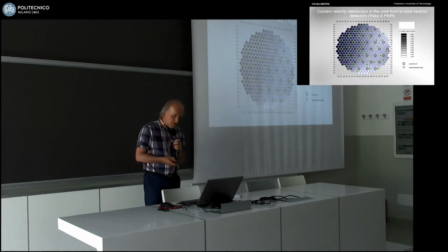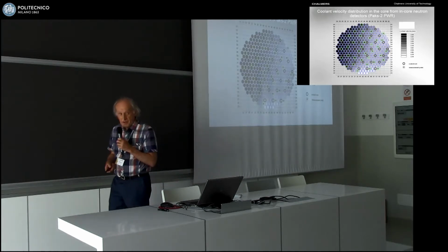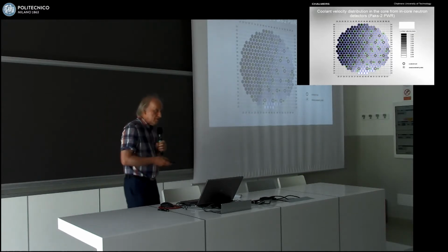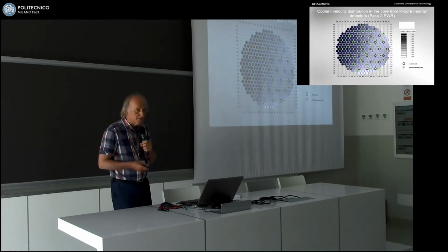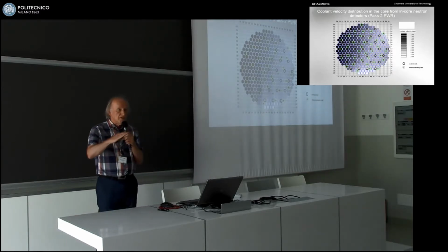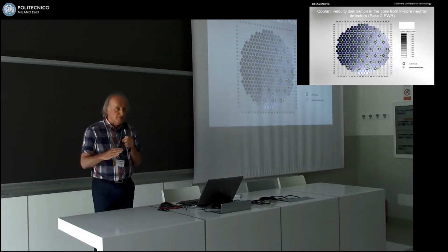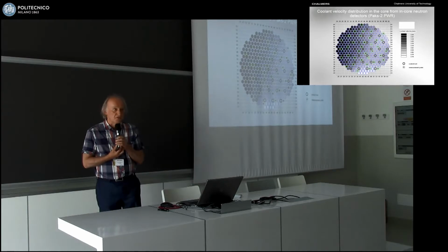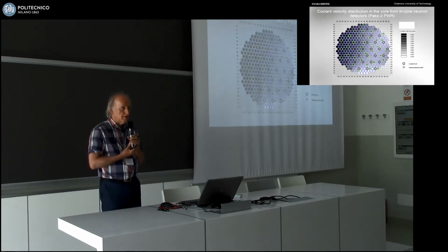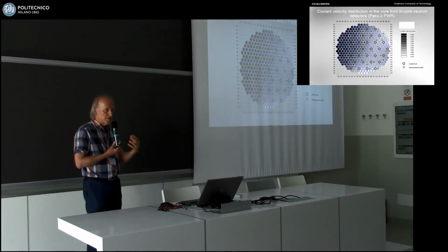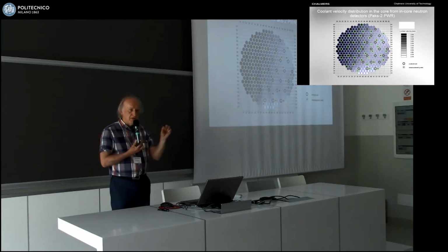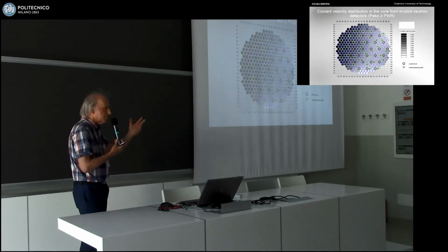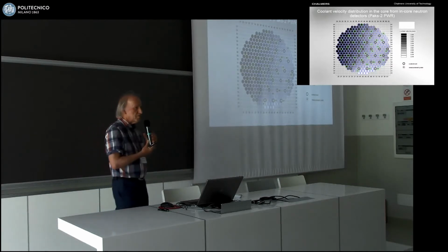I'm very proud of it because that's my Hungarian colleagues who did it in the PAKS reactor, in which there are in-core detectors. And from the signals of these in-core detectors, they found out that there is a non-symmetric distribution of the flow velocity. And why I think that this is a feat is that in a boiling water reactor, to measure the velocity is not complicated, because the perturbation is big. This is boiling. There's water. I mean, water or no water, that's a big difference. Here, it's minor temperature fluctuations which will affect the Maxwellian spectrum of the thermal neutrons. And still, it is possible to measure the velocity.